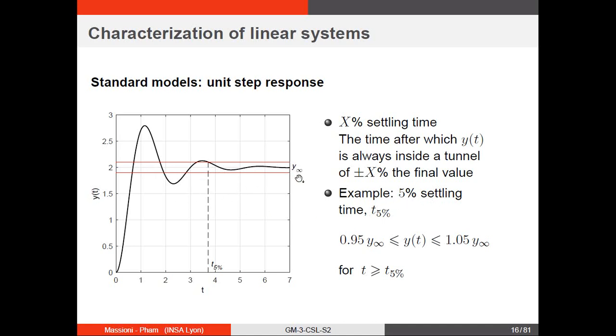We take y infinity, we take plus and minus 5%. We draw this tunnel here. So the settling time is the time when this signal enters this tunnel and never goes out anymore. So in this case it is here.